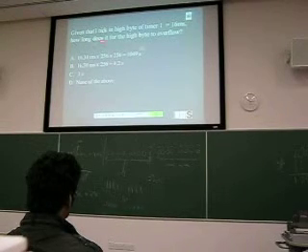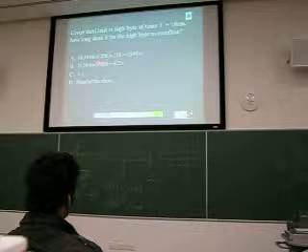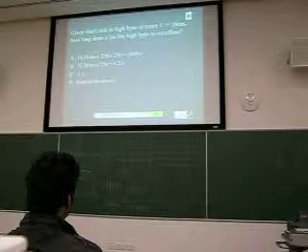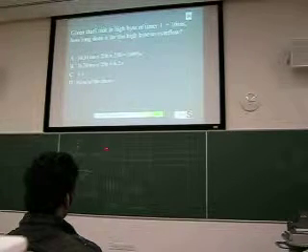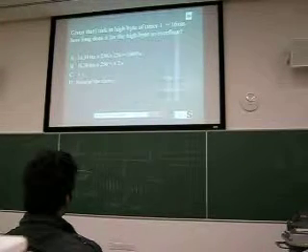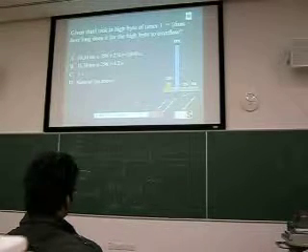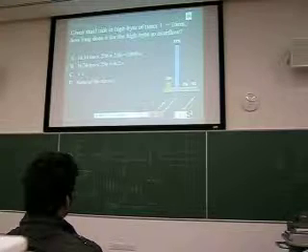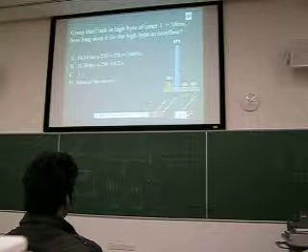How long does it take for the high byte to overflow? So we know that one of them takes 16 milliseconds. So how many numbers do we have here? 256, right? I'm going to stop here because it's pretty obvious. Which means that when the timer overflows, it corresponds to 4.2 seconds.